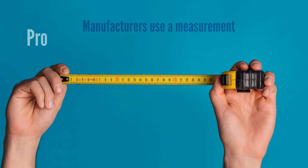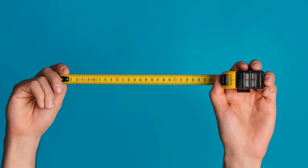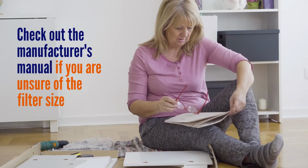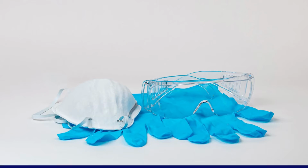A pro tip, keep in mind that manufacturers use a measurement called nominal size, which means measurements are rounded up to the nearest inch. Different systems may take different types of filters, so whenever you are unsure, check the manufacturer's manual for recommendations on how to proceed with replacing a filter. Also, given that these filters trap dirt, dust, and allergens, we recommend wearing a dust mask and gloves with a bag ready for the used filter.